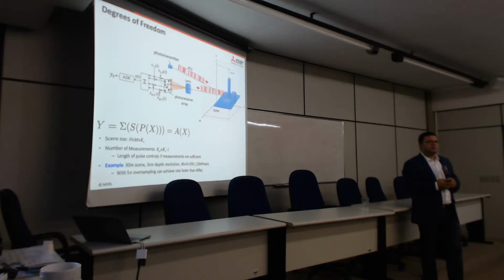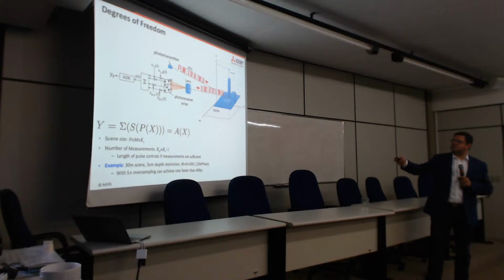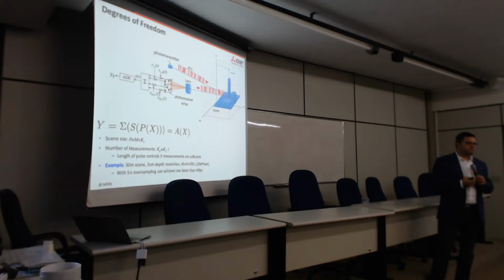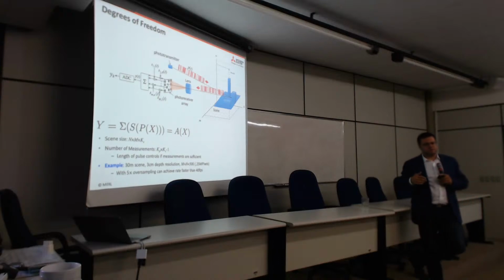Now, another thing that's interesting is when the codes become very long, randomized codes work. But sometimes it's better if you use a designed code, like an M code or something. What you need is that the code with itself has very low autocorrelation, except for the zero lag.